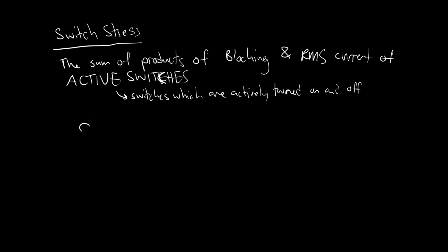So S, the stress, is equal to, we're summing over active switches, and it is equal to the blocking voltage of that switch times the RMS current of that switch. Right? So this tells you how hard the switch has to work. In a sense, cool.